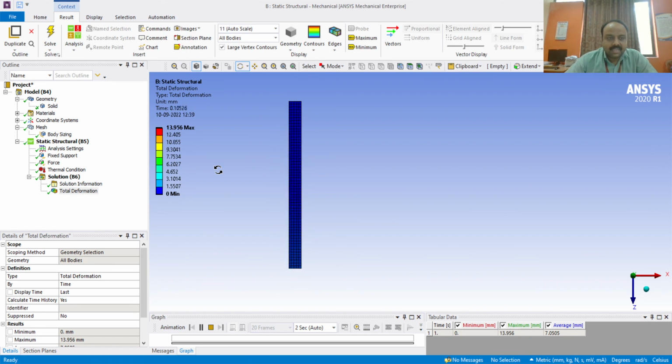The Young's modulus of steel at 22 degrees Celsius is about 210 GPa, and at approximately 900 degrees Celsius the same Young's modulus reduces to 70 GPa. Due to that, the whole structure collapsed. It is one of the theories behind the collapse of the structure.